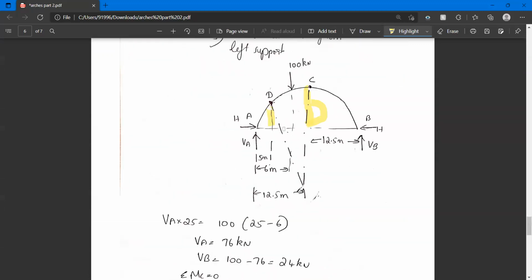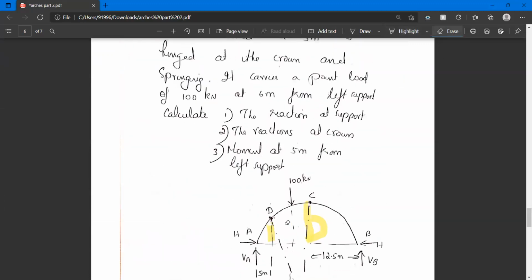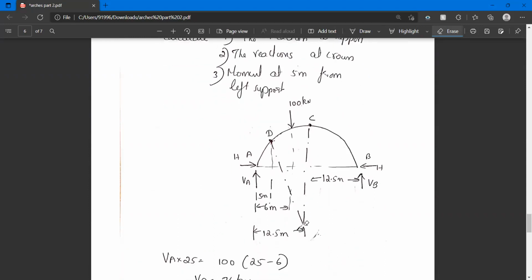Okay, just like this. H, you know, H is the rise. H minus the distance till this point. Okay, distance from C to center point is R. So this much distance, how we can find? This much distance is equal to R minus R cos theta.